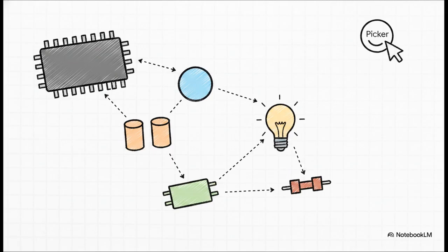Now, before we start wiring anything up, we need to gather our virtual components. Using the P button, that's the picker button on the Devices toolbar, you're going to search for these exact items: an AT89C51 or AT89C52 microcontroller, a push button, two 33 picofarad capacitors, a crystal oscillator, your LED, and finally, a 470 ohm resistor.